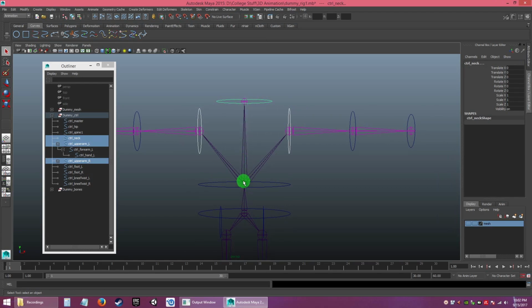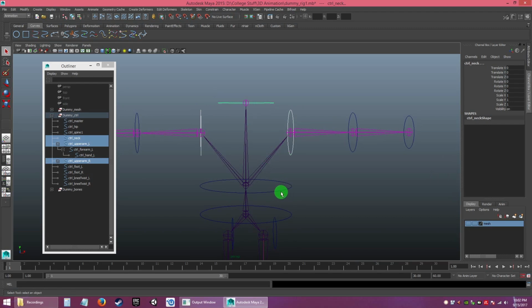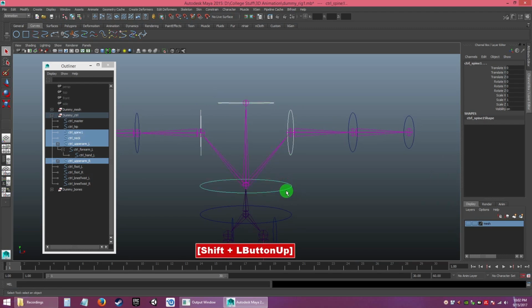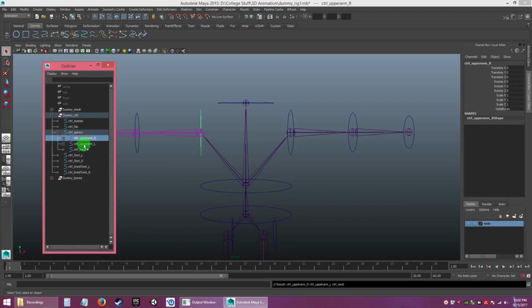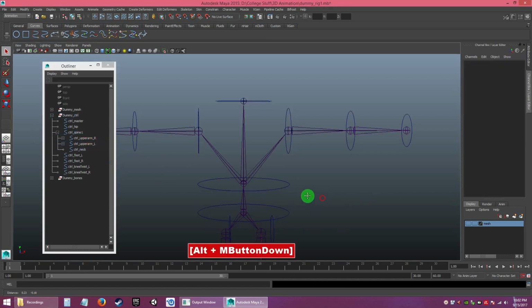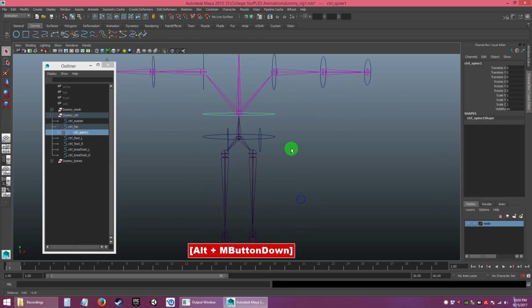Now both upper arm controllers and also the neck, you see where does it link to? It actually links to this bone, and this bone and this bone link to this bone. So this tree of controllers will be parented to spine 1. Select spine 1 as the last selection, the green color, and hit P. Ooh, see, now everything is inside spine 1. You open this, you'll see upper arm left and right, and also the neck. Then spine 1, select the hip, and then P.